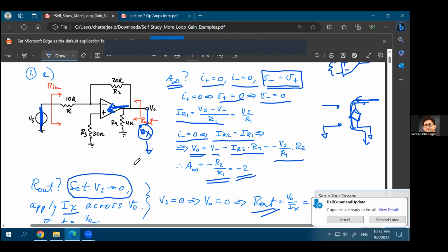What we are saying is that even if you have the voltage source over here, if you are pushing in a current here, what resistance will that current see? It will see 0 resistance. That's all we are saying here, that the output resistance is 0. You are not deactivating the voltage source, because if you deactivate the voltage source, you will not get any output in that case. Right?